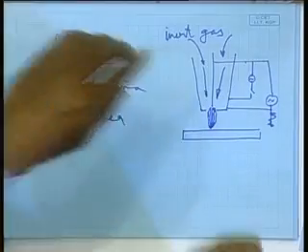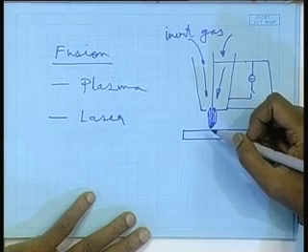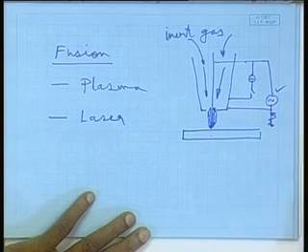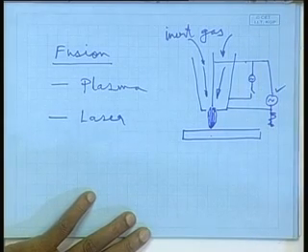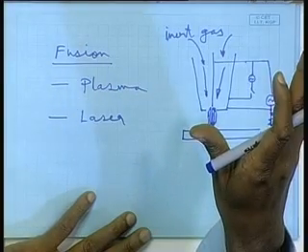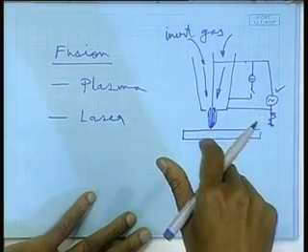So, in plasma cutting I can attain a very good cut edge. The quality of the cut edge that can be achieved is very high, nearly equal to that of mechanical cutting. And obviously, how much heat it can generate depends on the power, and that power can be varied by increasing the power of the power source, right. So, effectively it can cut any thickness of plate, that means much higher thickness of plate also you will be able to cut with a plasma torch.